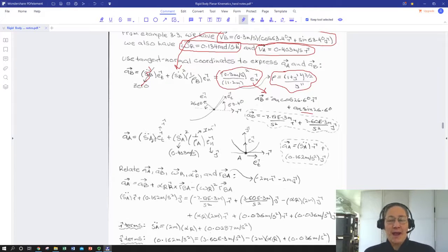So we've got whatever the tangential acceleration happens to be for point A, pointing in the tangent direction, which is also the i hat direction. Then we have its velocity at that point, which we solved in our previous problem, and we have a numerical value also for our radius of curvature. So we have an expression for acceleration of point A with only one unknown. We don't know the tangential acceleration, which is also the i hat acceleration.